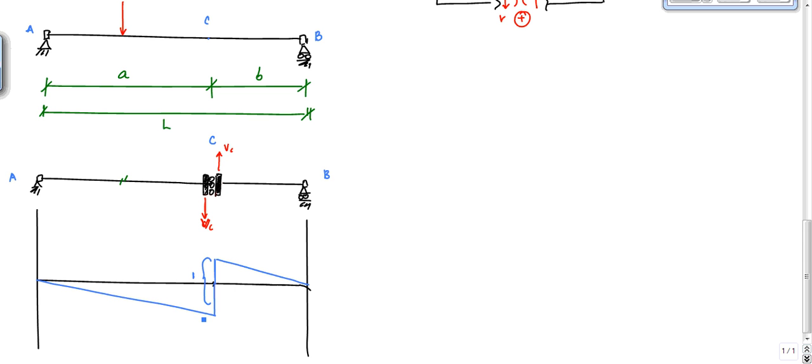But truly the deflected shape really looks like this. The deflected shape, actually, here, I'll draw it in purple this time. It's going to be like this, okay? And then I have to maintain here that the slope of this line has to be the same as the slope of this line here. And really, the deflected shape for this, as you can imagine, looks something like this, where these are still 90 degrees here and here, because as this member BC rotates up or moves up, it can't stay the same length.